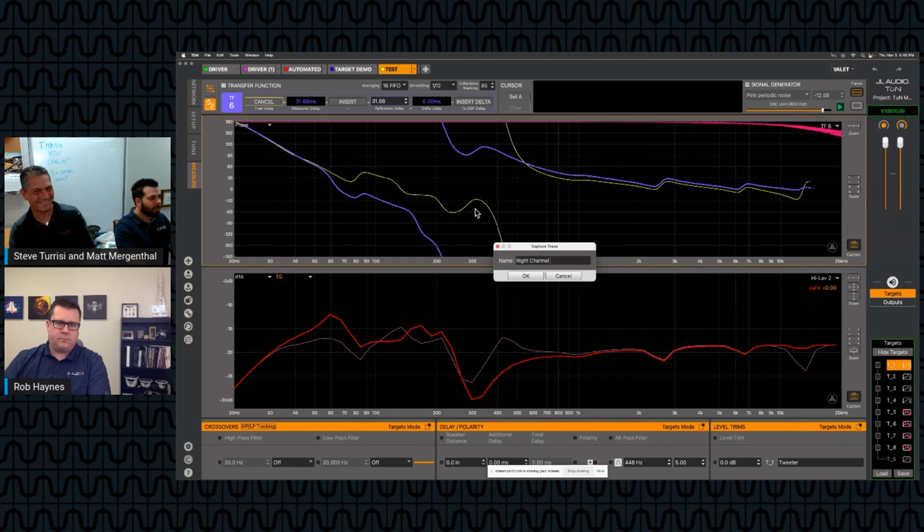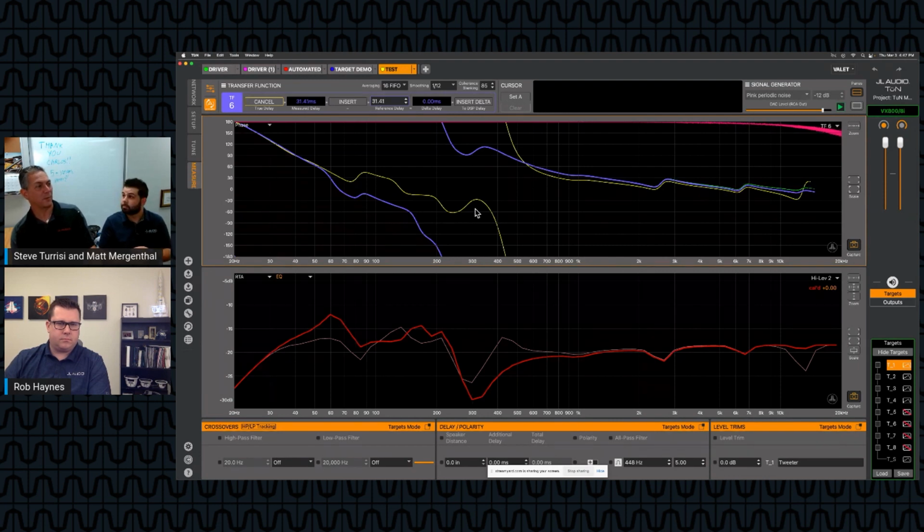Right channel phase. So the question here is, what can we do to fix this? Because there's a couple options, right? A couple different things we could do. But Steve, what do you think we could do to fix this? Well, one logical thing would be to put an all-pass filter on the opposite channel, but in this case, it would be on each channel at different frequencies. Would that help us? It likely would, actually. Although it sounds silly, putting the equal all-pass filter on the other channel would indeed create the same wrap.